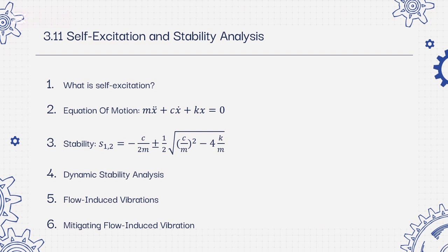Now, flow-induced vibrations, like those from vortex shedding, generate periodic forces. The shedding frequency is tied to the Strouhal number, which is almost 0.21. There is a risk of resonance if it matches a structural natural frequency. Mitigation includes dampers, for example, Stockbridge dampers on power lines, geometry changes, and ensuring that the design avoids critical frequencies. Proactive design prevents failures, emphasizing stability checks and energy distribution.